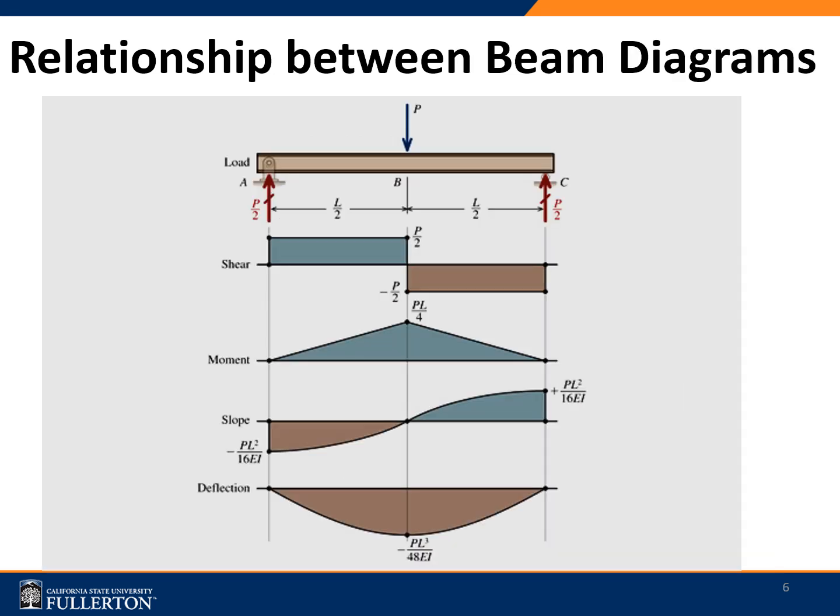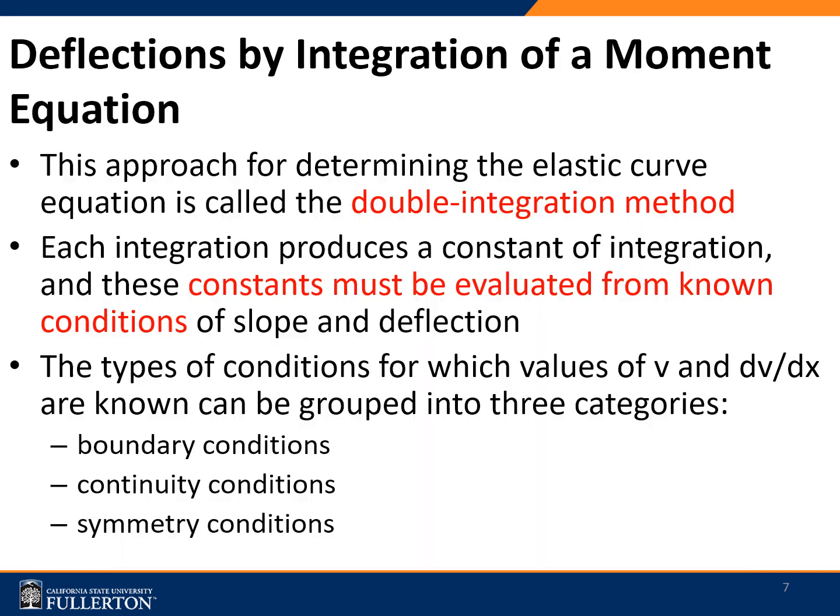You can see the figure over here. If you start with the applied load P, you could go backwards. So let's start with the deflection. If you take its derivative, we'll get the slope, and then we take one more derivative, we get the moment, and so on, and we reach the load. So in the integration method, what we do here is we start from the load, we integrate, and we get the successive quantities: the shear force, bending moment, slope, and then finally the deflection. What we need for this integration, we will see in the next slide.